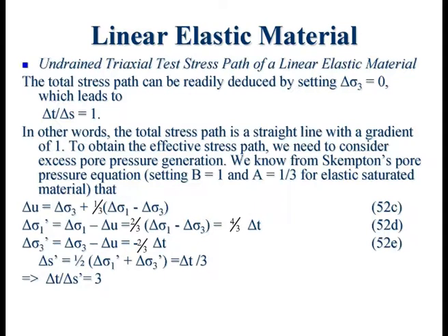Now, T and Q are actually measures of the shear stress. Okay, T is called the deviatoric stress because the Americans call it deviatoric stress, and it was started by MIT. So it is kind of sacred in America. All right. Whereas Q was started in the UK, so the British call it deviator stress. When you do a triaxial test and plot a stress strain curve, the stress you usually plot is the deviator stress, the diameter of the Mohr circle in the triaxial test. So that is the deviator stress. Now, they are both measures of the shear stress.